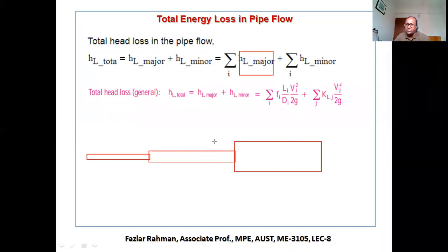That means Darcy-Weisbach friction. So over here flow might be laminar, over here might be turbulent, over here might be again laminar. So that's why over here you give hLF1, hLF2, hLF3. So that's why we use the hL measure and summation.